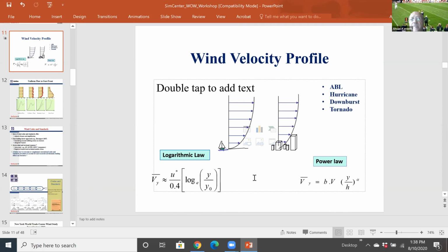Well, large offshore structures will be somewhere even on the left of this. There the profile would be a little bit fatter than this one, typically with an exponent alpha of 0.1. By the time you reach the coast or very near the coast, it might be 0.12, 0.13. So the profile for offshore structures is totally a different area because you have interaction with waves also. So that's a little bit more complex. But if you just want to use basic design procedures, the profile would be even more.